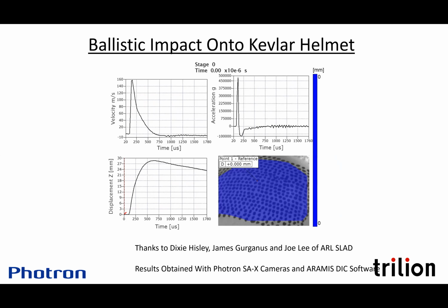This is something I was just talking to some colleagues about, our new frequency domain tool that I just gave a hint at in today's presentation. We're then working directly in the frequency domain. Our effective displacement sensitivity goes up, so we can pull mode shapes out at higher frequencies than we would be able to with just the brute force time domain measurements.